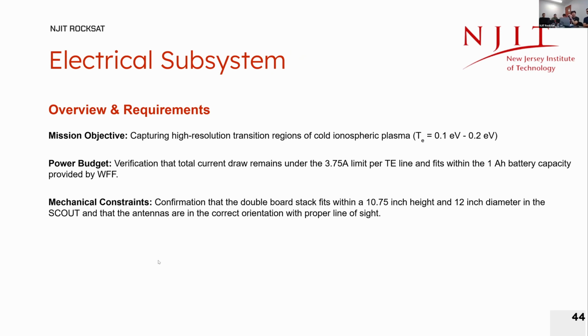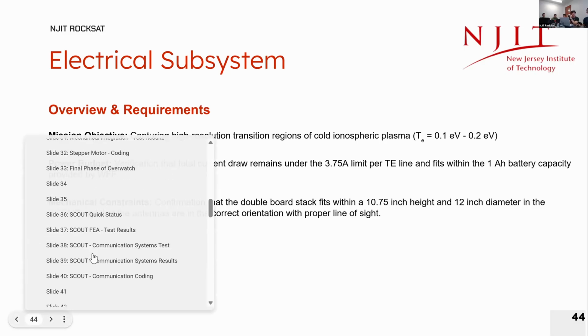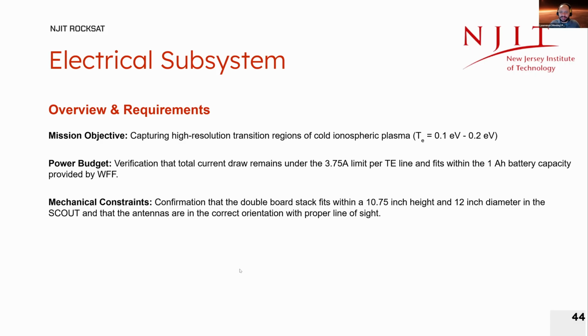Okay. I believe we discussed inrush current on the last one, which NNU now takes the lead on, as far as the amount of amperage they're going to take for that amount of time. You were looking at like 65 amps for like 200 microseconds. That was the initial testing. I forgot what exactly we changed in the simulation, but it was more realistically going to be 27 amps. But it's very, very short, less than 50 microseconds, so it shouldn't be too much of an issue. The fuse should be able to handle it. Yeah, you'll be fine.